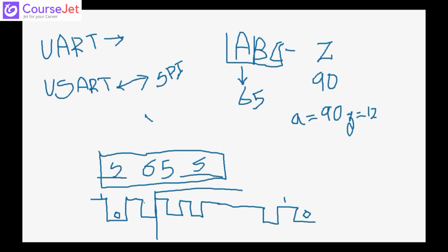This is also a high to low signal. This is also 1 and this is 0. So if you are sending something like 1 to 0, how will it understand that my data is starting here? That data framing is already set by your register, which we will see in the register section. But basically, whenever you send a high to low signal, it will understand that this is the start of data and the next 8 bits are my data.